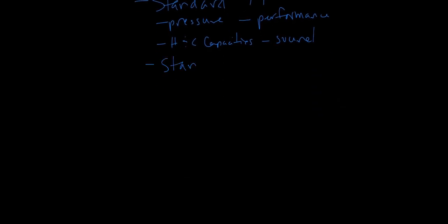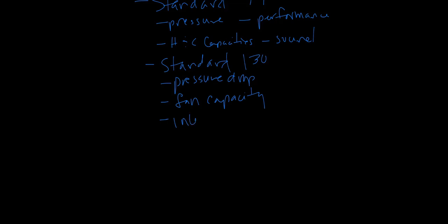Then we have Standard 130, which is the method of testing air terminals. This standard is also being revised. This standard will test for pressure drop, fan capacity, inlet K factors, temperature sensing, and inlet conditions.